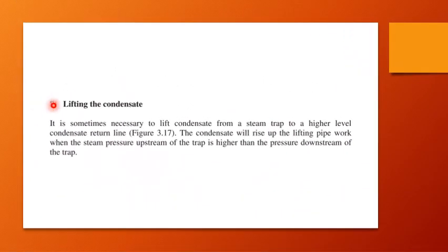Now, lifting the condensate is also a concern when you design or install the steam traps. You should keep in mind that if there is a requirement of lifting the condensate, proper arrangement should be there. It is sometimes necessary to lift the condensate from a steam trap to a higher level condensate return line. So in that case, you need to have proper arrangement.